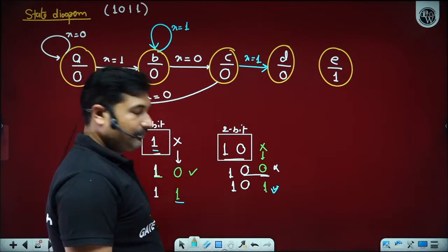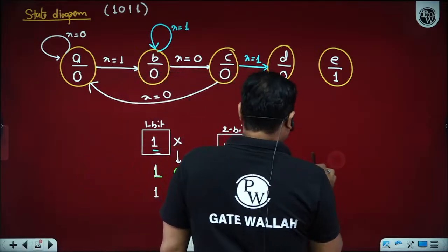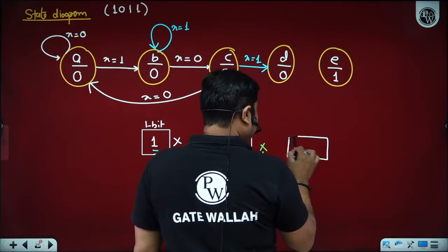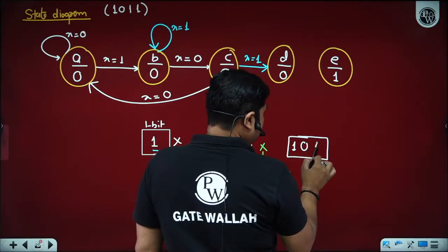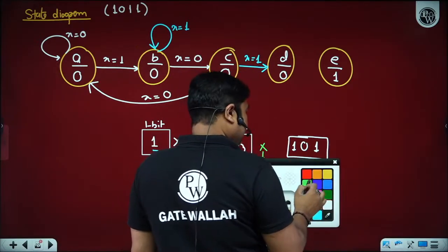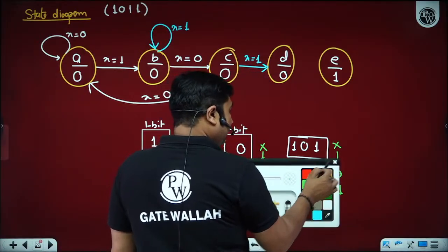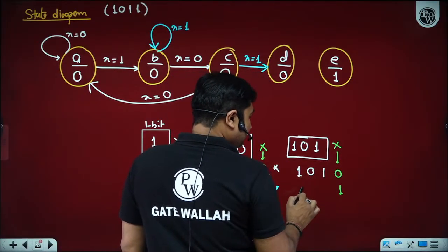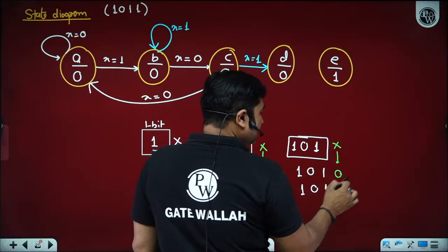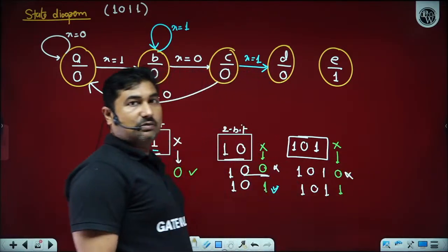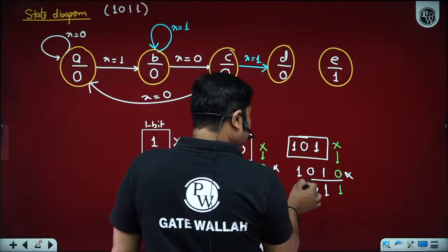In the same way, if you are on state D, it means already 3 bits in a sequence got detected. Is it okay? Now, next input x can be 0 or 1. Yes, sir. 3 bits are already detected in a sequence. If you got a mismatch, this is not the required sequence. So compare the last 3 bits with the 3 bit state.